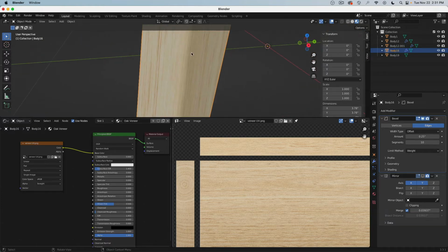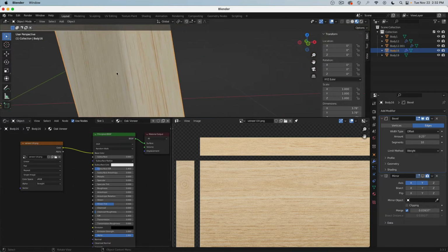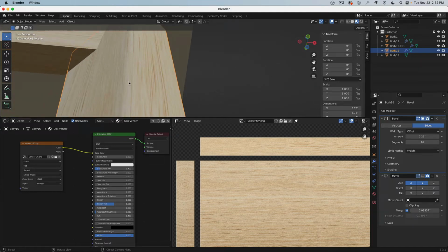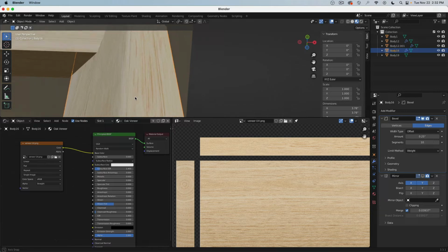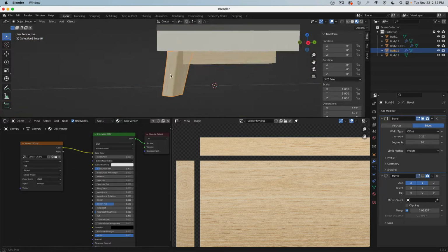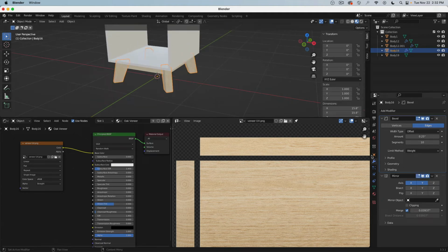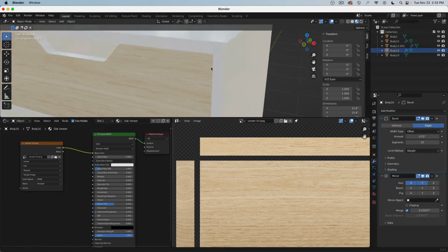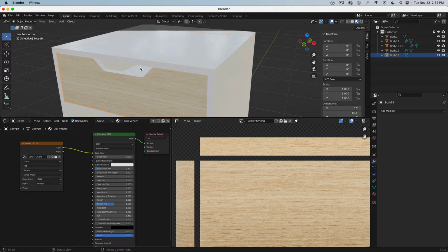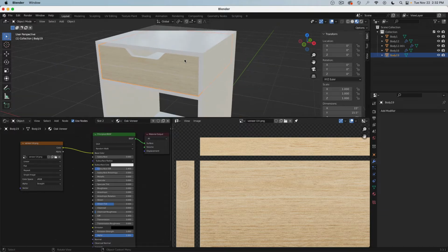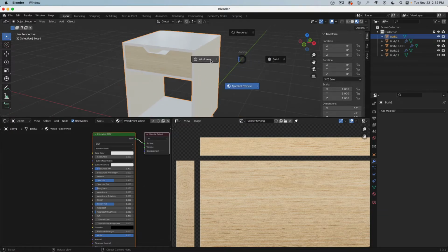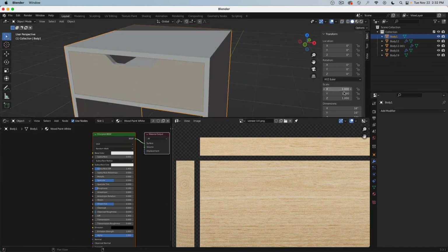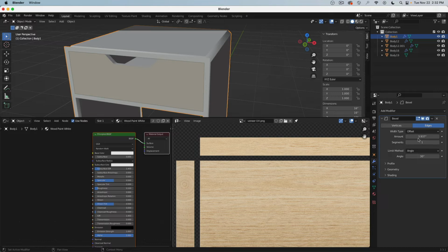And the nice thing is this command then blends between the textures, and there is actually a noticeable line if you really look for it, but it's so well calculated nobody's going to see it. So beautiful. Turn this on. Now talking about this bevel modifier, let's go to here. We see that we have the box and there's no gap, which is kind of like not realistic. So let's add small fillets to it. Z in wireframe or Z in solid. Yeah, solid is good. Bevel modifier, maybe 1 millimeter and 1, it's fine.